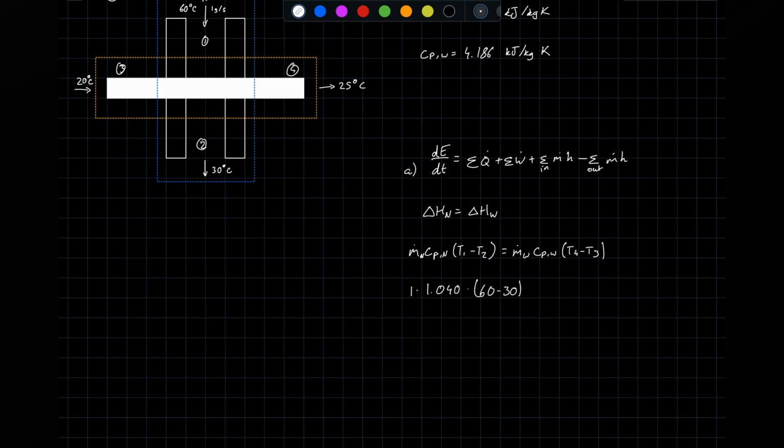Well, if you're just going to be adding 273.15 to each number, then subtracting the two numbers, the difference will be exactly the same as if you just keep it in Celsius for now, because the conversion is linear, which means that the subtraction will also be exactly the same. So that's why we can keep just the Celsius.